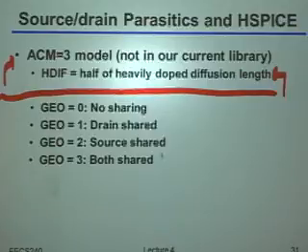Typically you would do this before you even had any of the layout, and you just enter these parameters to try and get a rough guess as to what things actually look like. Of course, once you have the real layout, the real number should be entered into the model so that it gets that correct. That's also why I didn't turn it on in our particular model, because I want you to think a little bit about what the real areas and perimeters are of whatever topology you would really be using. Is that clear? Okay, great.